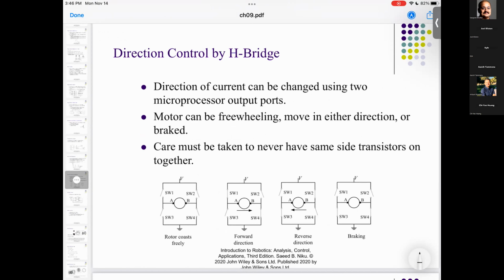And again, the idea is you can have a very small motor that is running at very high RPM. And then if you use a heavy gear reduction, just like a planetary gear drive shown over here, this is the planetary drive, then that small motor can supply very large torque. Because please understand that small motor is supplying low torque, but the speed is very high, say 10,000 RPM. And all of a sudden you use some kind of transmission and this speed drops down to say 1 RPM. All of a sudden you get a 10,000 times multiplied torque output. So that is the purpose of the transmission.